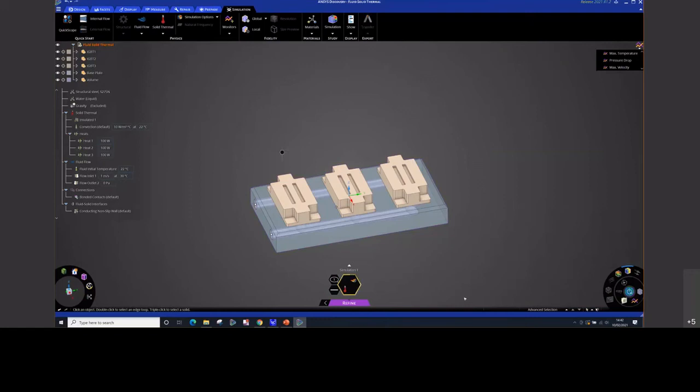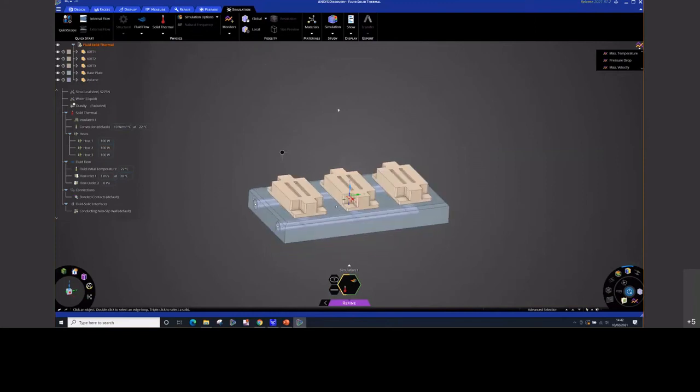And again, this is based on a fidelity that I've got set here, so just like a mid-level fidelity, and it will use Ansys' automated meshing to define a mesh. But please remember that you can also define the mesh manually. Obviously you can increase the fidelity bar, but you do have your local and global mesh settings here. So you can use those to define the mesh yourself.